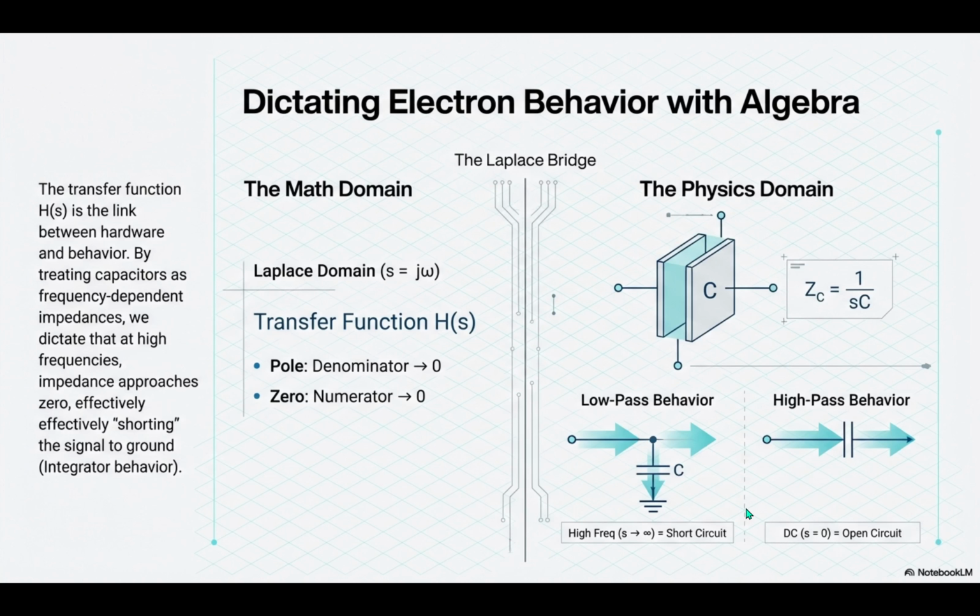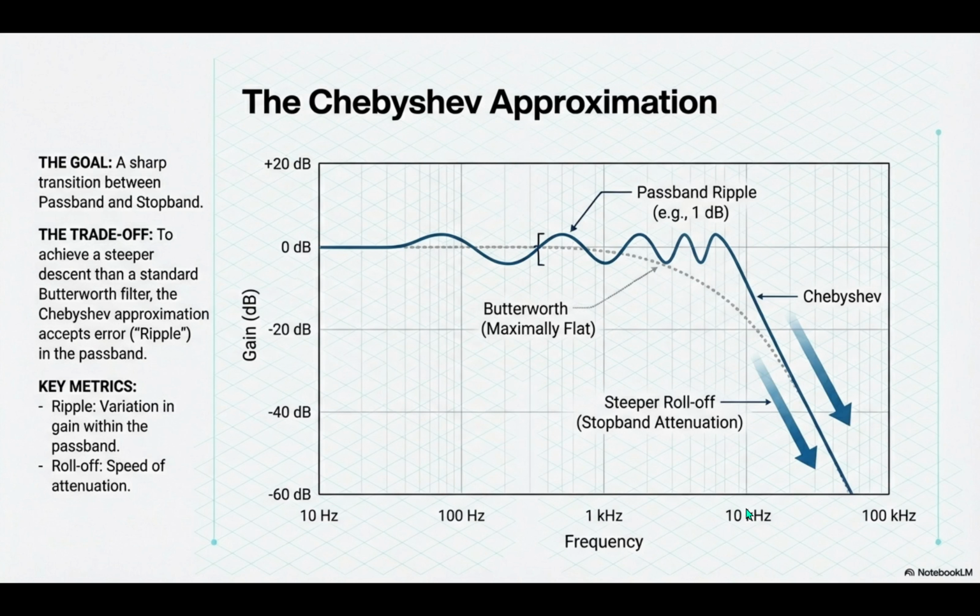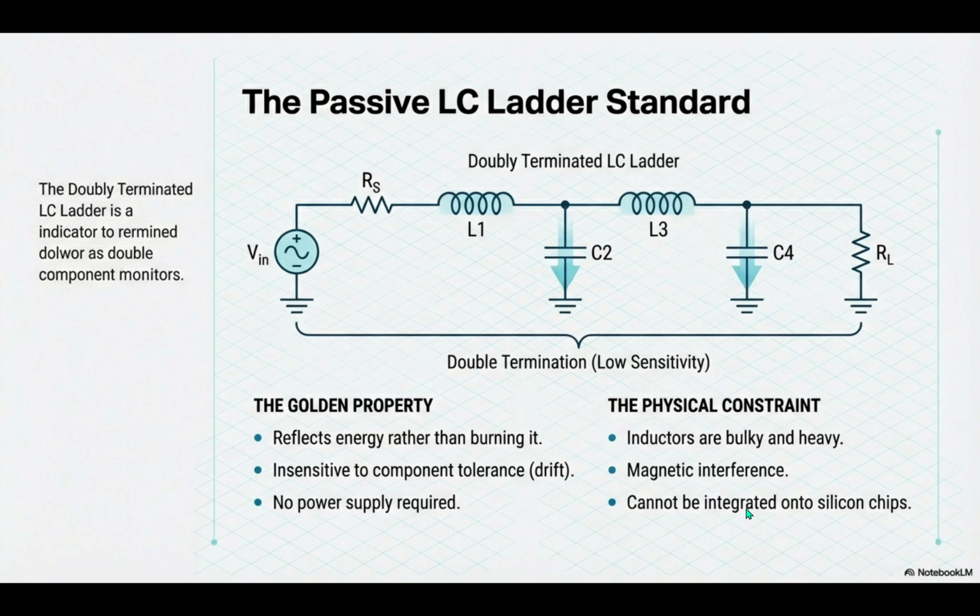They are lossy. Lossy meaning the signal gets quieter. Always. A passive filter can never, ever boost a signal. It can only carve away at it. The resistors burn energy as heat, so your output is always weaker than your input. And if you chain a few together, you're left with nothing.